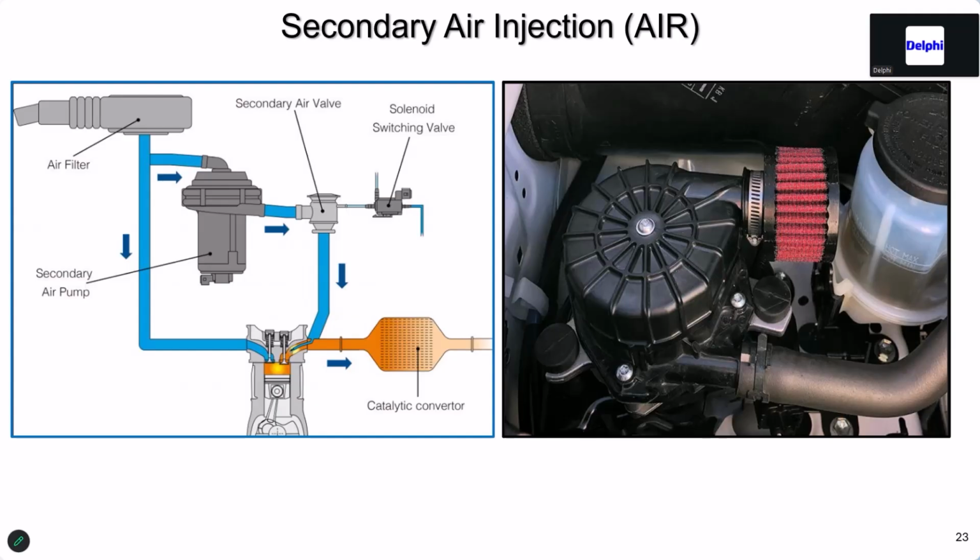If you're not sure, generally give it a cold startup, run the test. The older GMs, some of them, you had to get it started up and get into a fuel trim cell, which could have been 500 RPM, 1,000 RPM, but you had to get into a certain window to test it. Most cars today, start up, let it idle, secondary air should run.